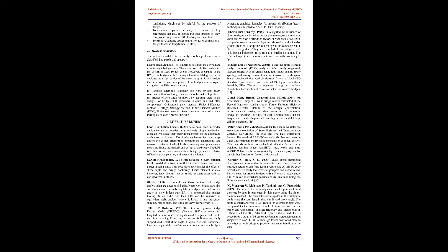The behavior of a skew bridge is quite dissimilar from that of a straight bridge. In non-skewed bridges, the load path goes in a straight line towards the support in the direction of the span. In skewed bridges, this is not the case. For a solid slab skew bridge, the load tends to get a shortcut to the obtuse corners of the bridge. In addition to introducing problems in the design of details of the deck, skew has significant effects on the deck's behavior and critical design stresses.